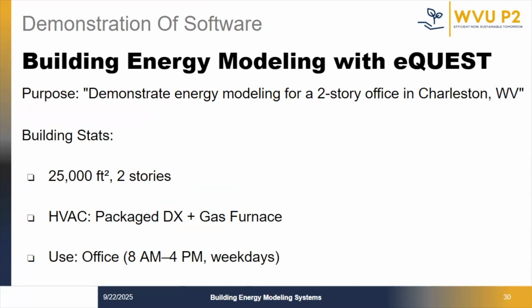This model simulates a typical operational setup, including a package DX and gas furnace HVAC system with occupancy limited to weekdays from 8 a.m. to 4 p.m. The purpose here is to showcase how energy modeling like eQuest can be applied to real-world scenarios, providing insights into energy use, system performance, and potential efficiency improvements for commercial buildings.